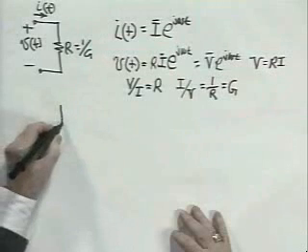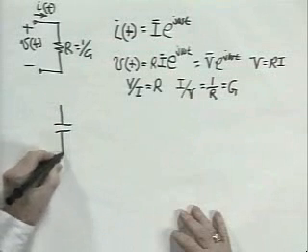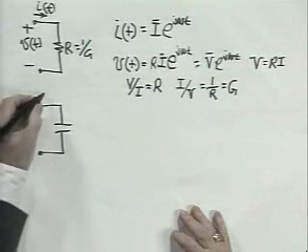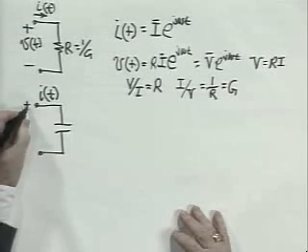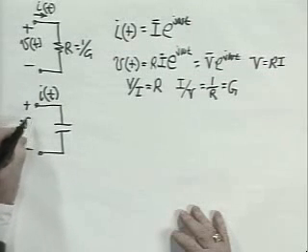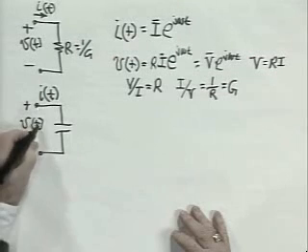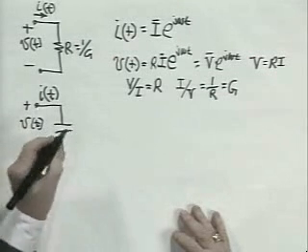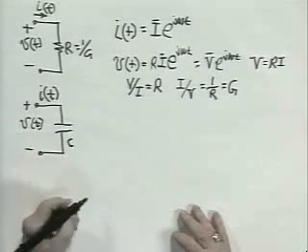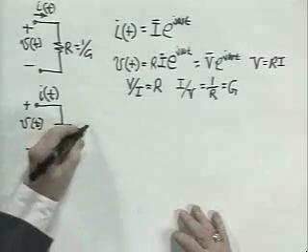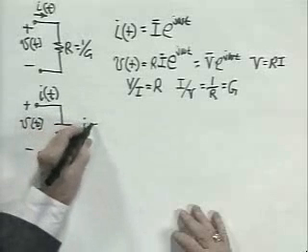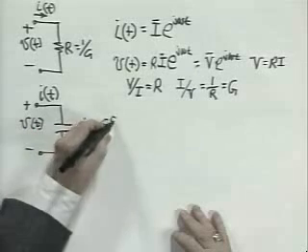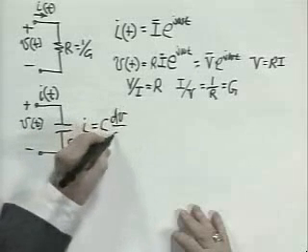Now let's look at a capacitor. Same definition of terminal variables, associated variables, as we always try to do to keep the sign straight. A current and a voltage, either of which can be regarded as applied and the other as response. This is a capacitor of value C. And as you know, the current-voltage relationship of a capacitor is that I equals C dV/dt.